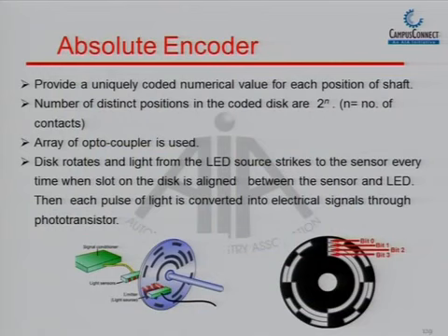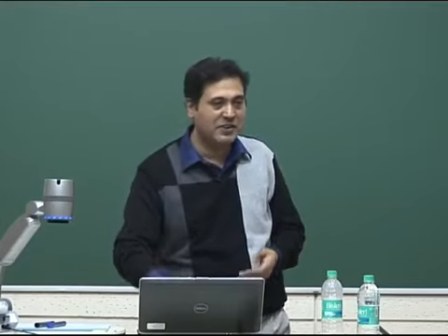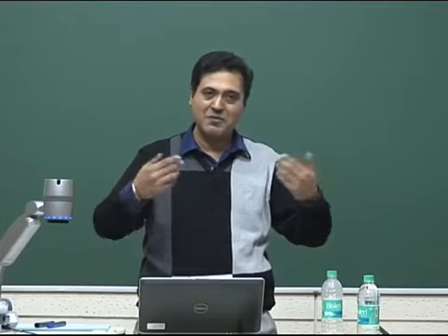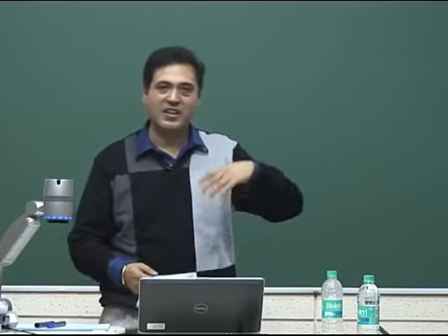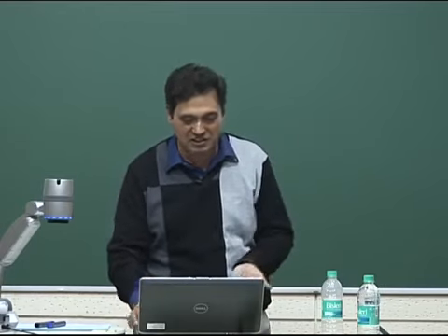Now if we talk about absolute encoders, an absolute encoder also has a disk. This is a disk of an absolute encoder. These are different bits: bit 0, bit 1, bit 2, bit 3, because absolute encoders work on the principle of bits, binary. If it is a single-turn encoder, you have 16 bits. If you have a multi-turn, it has a total of 30 bits. So in case of power failure, each of these bits is either 0 or 1. When the power comes back, the same 0 and 1 positions are always maintained. That's why we do not need to go back to the home position.